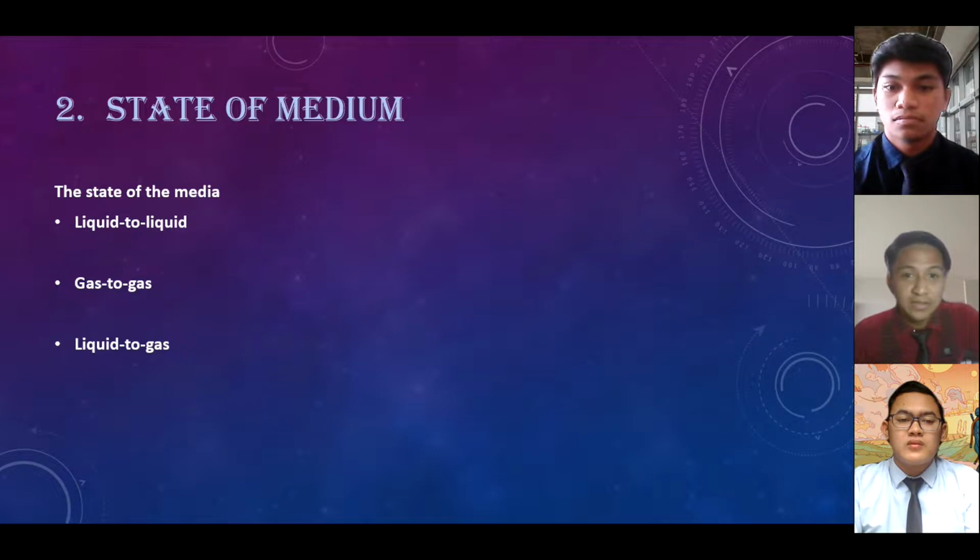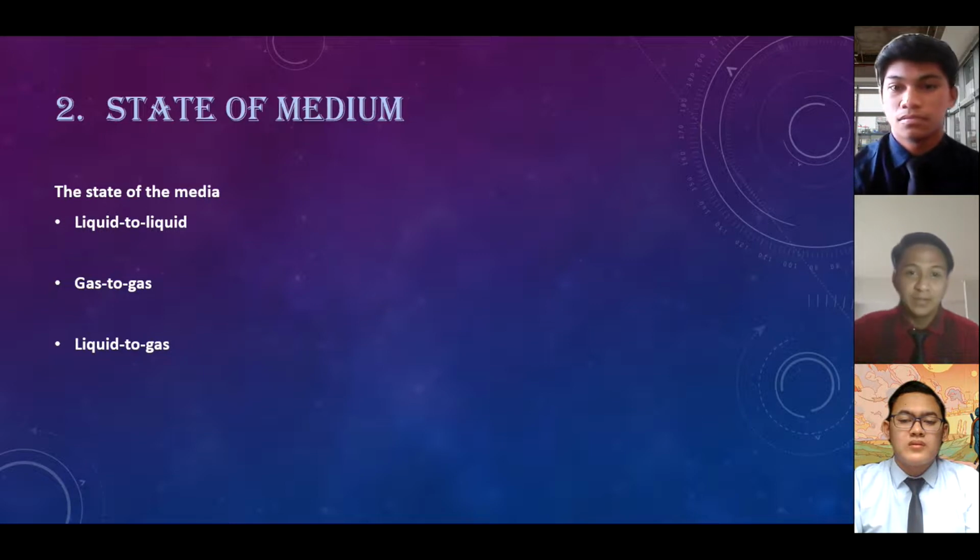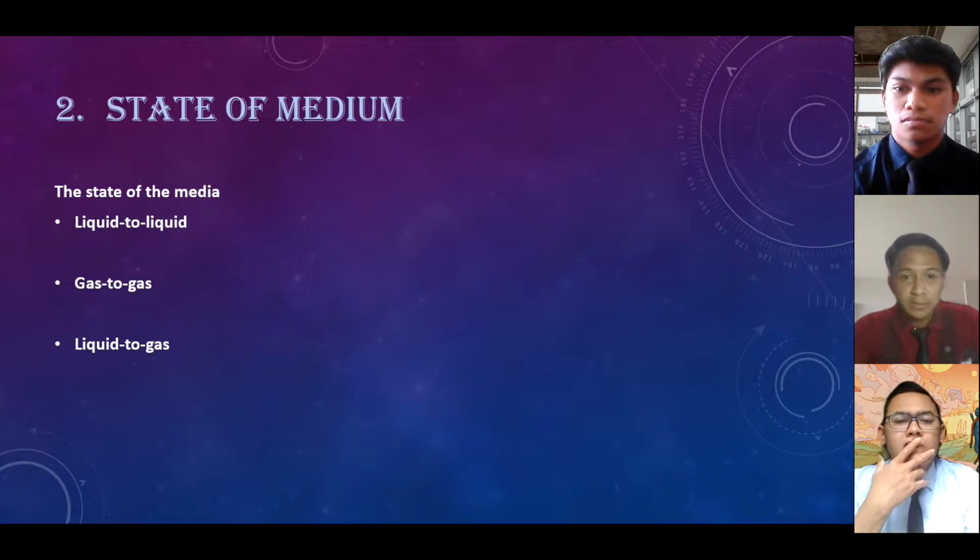Next, gas to gas. Heat exchangers like air preheaters in steam plants and helium-cooled reactor gas turbine plants have to be mentioned. This device operates with heat transfer coefficients that are between 10 and 100 times lower than the coefficient of liquid to liquid exchangers. Gas to gas exchangers are generally much larger and heavier if the same amount of transferred heat is demanded.